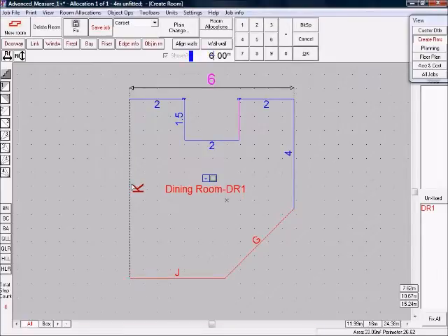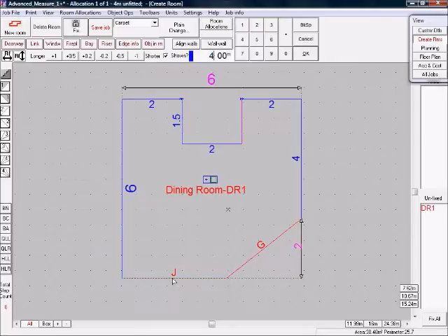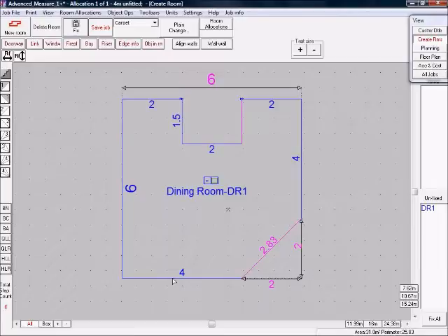The diagonal wall has an up dimension and an across dimension. You can see the up measurement has been deduced. Now enter wall J as 4 metres and notice that the system has deduced the across dimension and both the slope and length of the diagonal wall. Our space is now fully dimensioned. In this case, we didn't have to put in any dimensions for the diagonal.